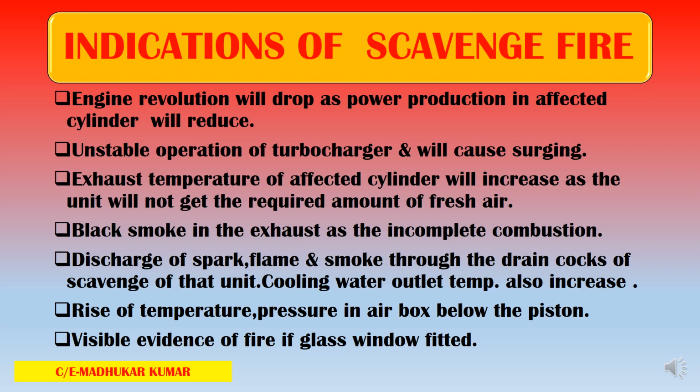Black smoke in the exhaust, as this is all leading towards incomplete combustion. So you will have the black smoke indication in the funnel. Discharge of sparks, flame and smoke through the drain cocks of the scavenge of that particular unit. Cooling water outlet temperature of that particular unit will also increase. Rise of temperature and pressure in the air box below the piston will be one of the indications, meaning the temperature will rise in that particular area, zone or unit.